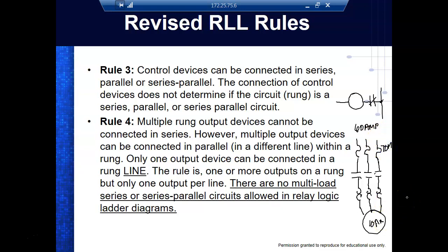But what happens if the motor stalls? Is the fuse going to blow? No, because it'll pull 60 amps. My fuses are rated to allow it to start and then give it some overhead, so the motor would sit there and burn up. So what we have is these sensors in what we call a motor starter that senses overcurrent over time.